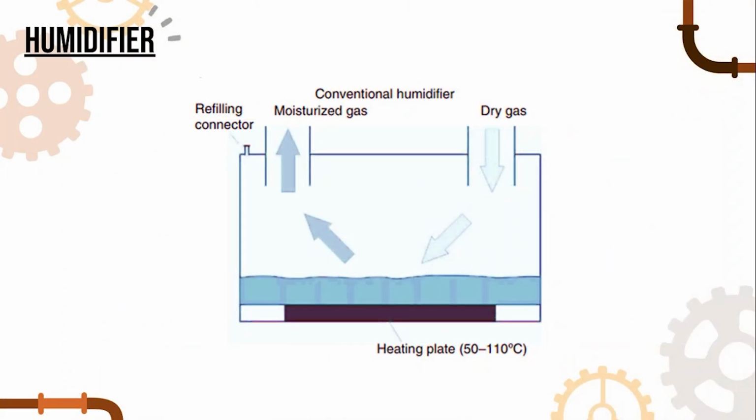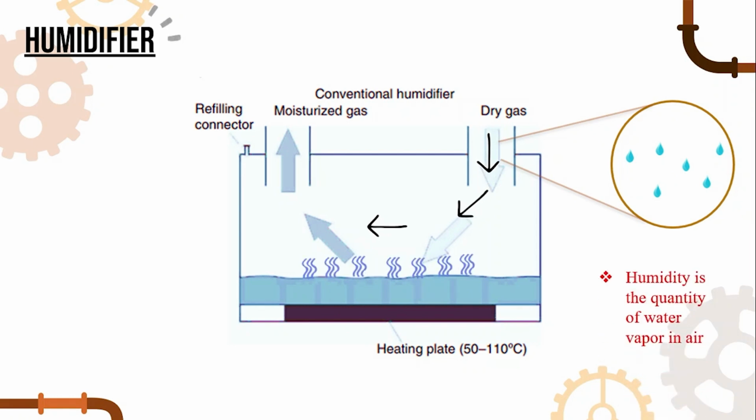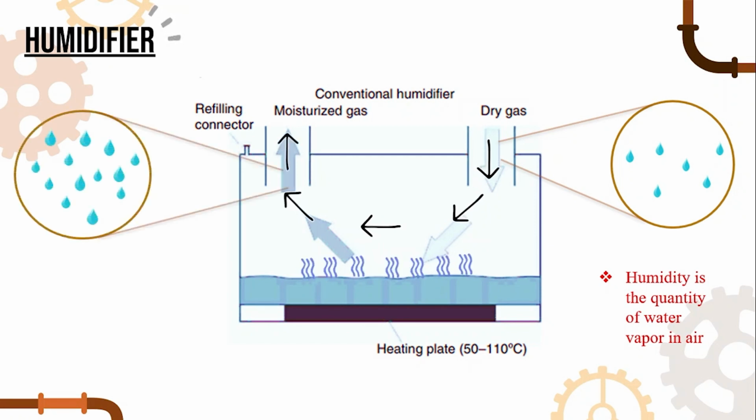Let's see an example. First, the air will flow into the humidifier. Then, the air will be in contact with the water. At this moment, water either takes significant heat and turns into vapor or evaporates itself due to low humidity in the air. Next, as the water vapor separates from the liquid, it is carried away passively or actively. This is the mass transfer process. The water vapor is then transported by the airflow out of the outlet. As a result, the outlet air has become more moist and has higher water vapor content than the inlet air.